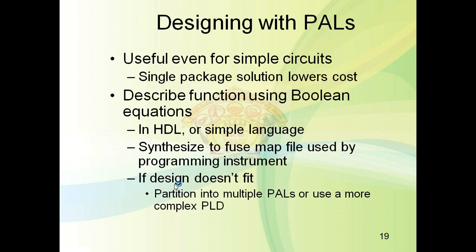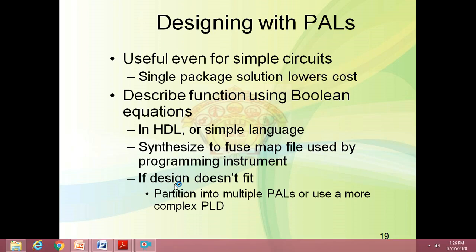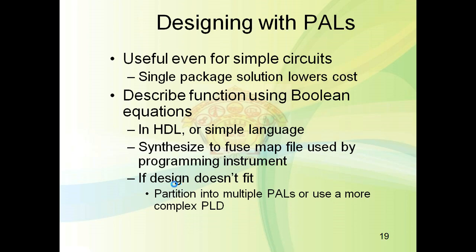Here we need to describe the function using only Boolean equations, expressed in an HDL language. Then the synthesis tool transforms the equation into a gate level circuit, which is verified by the test bench.